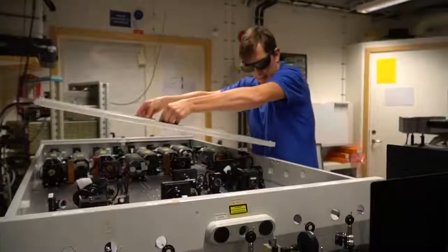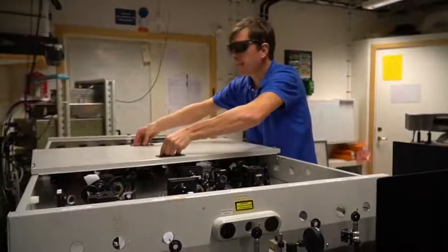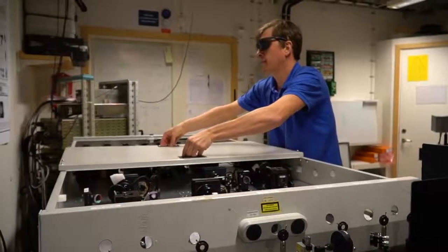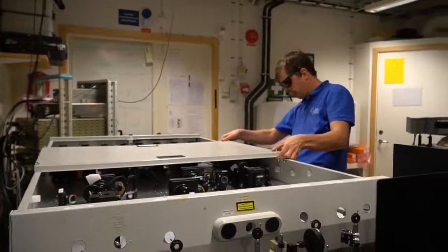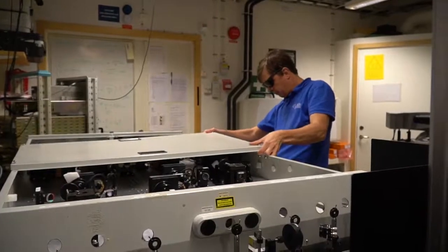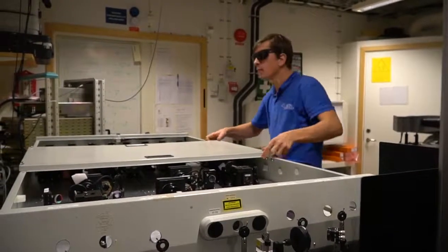Make sure that the laser is enclosed. The material you use to enclose the laser, and also for the beam dumps, must be made out of material that will not ignite or melt if hit by the laser beam.